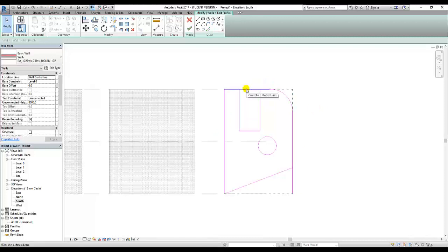One of the things that you'll find you do quite a lot when you use this pick lines tool is keep picking lines. You think, well, I've picked enough lines, and then you start clicking on other bits and pieces, but this pick lines option is still activated, and you'll overlap lines quite a few times. So when you try to create boundaries, you can't create them because there are extra lines in the way, and it can be frustrating. So I've got to trim out to this.